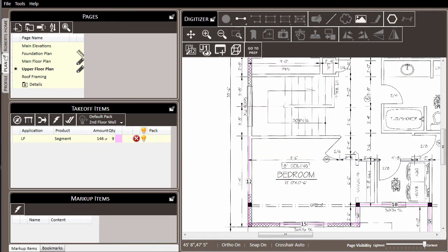We finish around the outside of the building, tracing all of the 6-inch exterior walls that are 8 feet in height. As noted before, we left off this wall by the stair framing since it will be a different height of wall. Whenever a wall is a different height, you'll estimate that as a separate wall assembly.